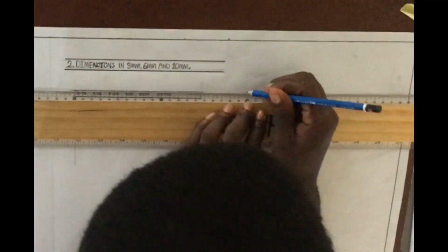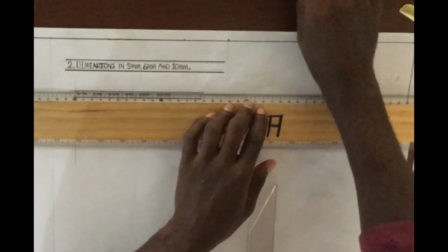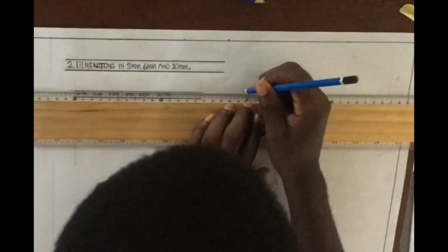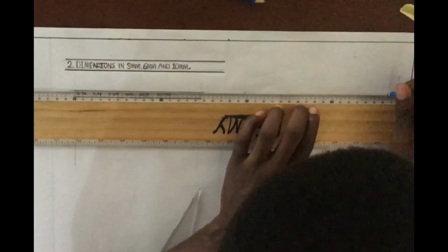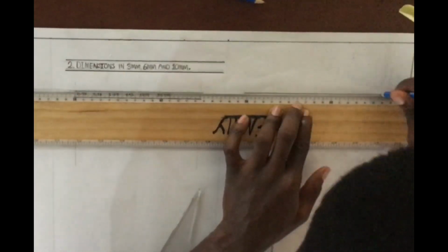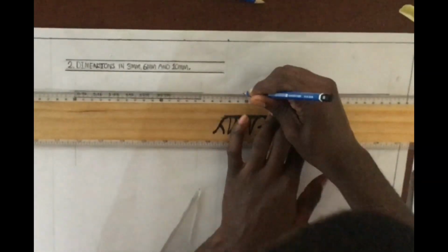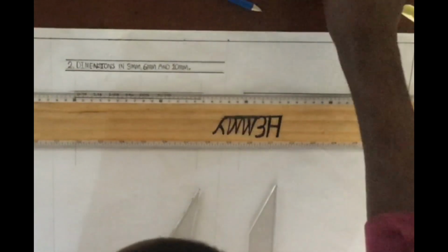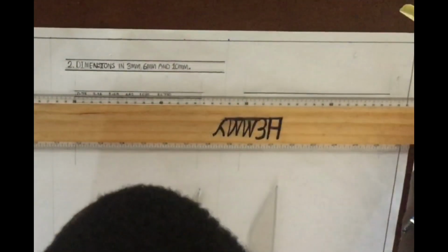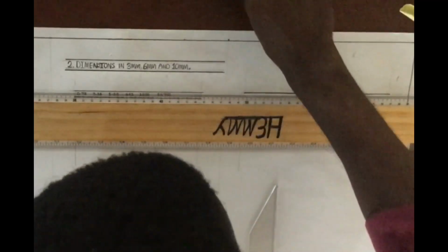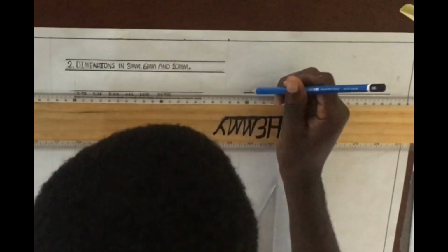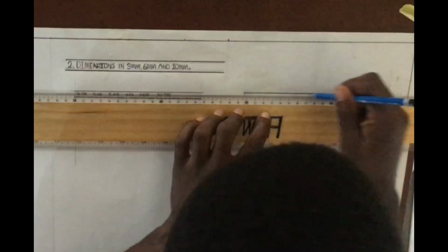I take thick continuous line at first. I'm actually projecting the other ones we've done earlier on. So thick continuous line at first, then followed by our thin continuous line to demarcate our 3 millimeter guideline. Please make sure it's a thin continuous line.